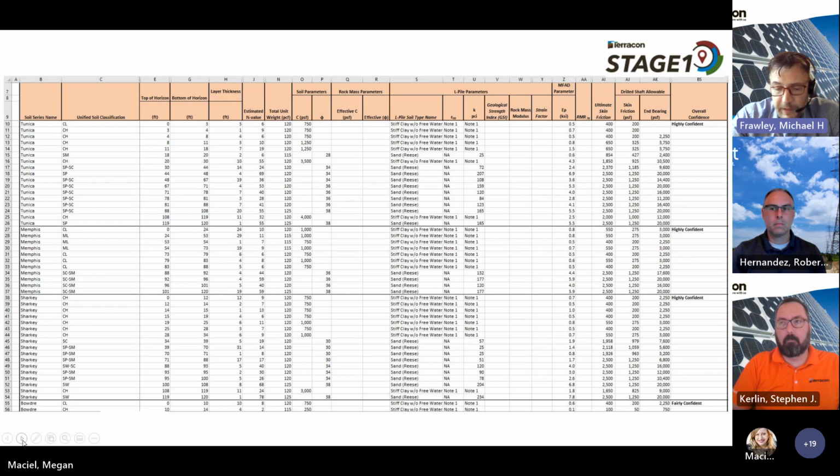Also, sometimes what we're finding is that these T-lines, of course, are going through just very remote stretches of the country. What we've actually started doing is saying, well, we have data for about 90% of your line. We can make very accurate predictions over 90%, but there's this 10% where we have never drilled. No one has. We're able to stage a preliminary exploration to say, if you're going to do a desktop study, would you be willing to do 2 or 3 borings as well? Because that's going to give us enough data to really inform this to make a really good decision. And it's much cheaper to do 2 or 3 borings than 200 or 300 as more of a planning tool.